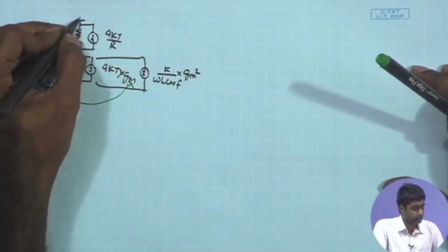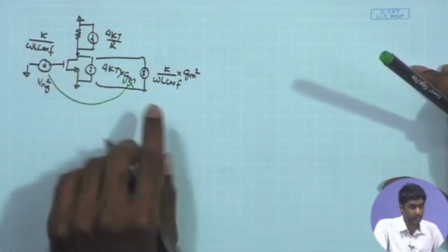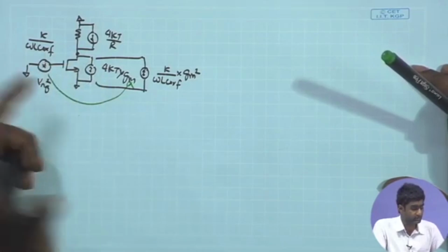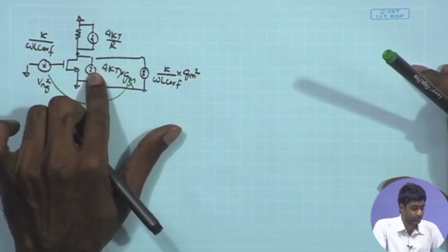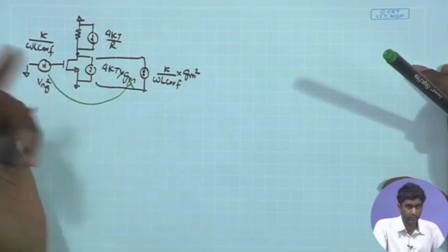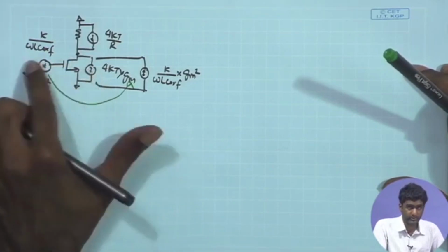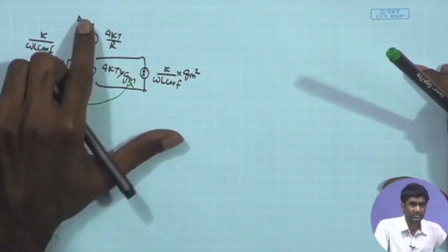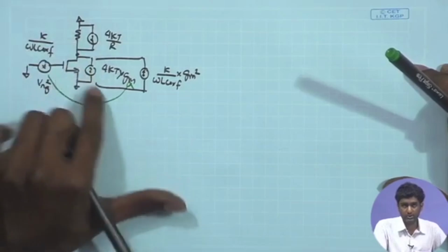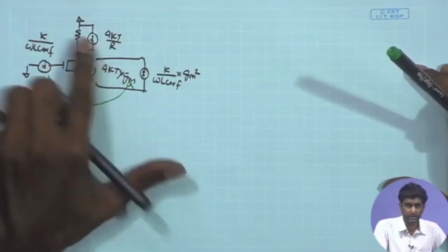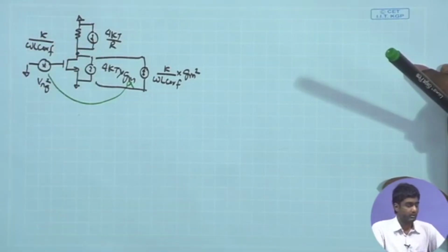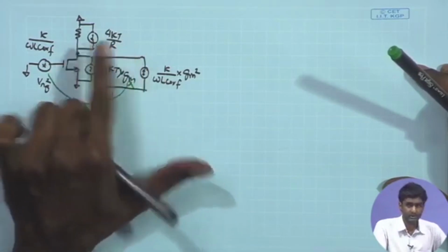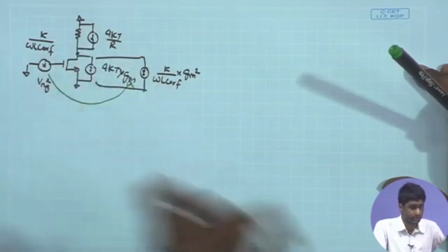And as a result, if I look at the AC analysis, the overall voltage over here, I need to take up the summation on the square values. As we have discussed earlier, if you have uncorrelated noise sources, like the noise source at the gate is uncorrelated with the channel current noise, because the mechanisms are different, their origins are different, therefore, these two are uncorrelated noise sources. Likewise, the resistance noise is also uncorrelated with the other noise sources, therefore, these are three independent uncorrelated noise sources, and therefore, in order to get the final output voltage, I need to just take the sum of their mean square that I am automatically obtaining from this combination.